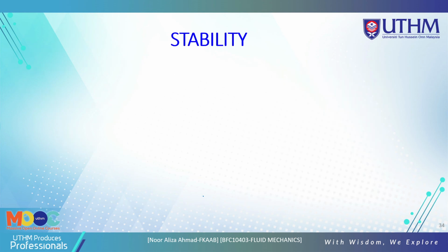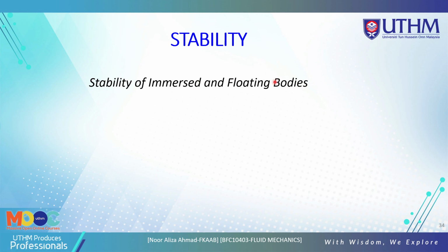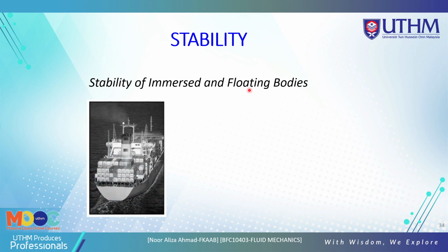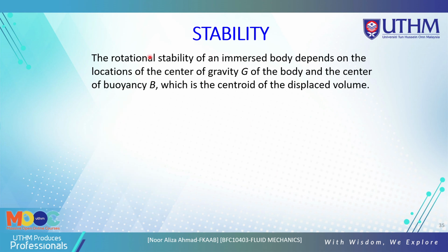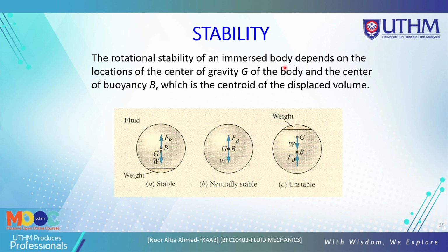Now we go through stability. After we learn more on buoyancy force, you must know the stability of immersed and floating bodies. For floating bodies such as a ship, stability is an important consideration for safety. The rotational stability of an immersed body depends on the location of the center of gravity, G, of the body, and the center of buoyancy, B, which is the centroid of the displaced volume.